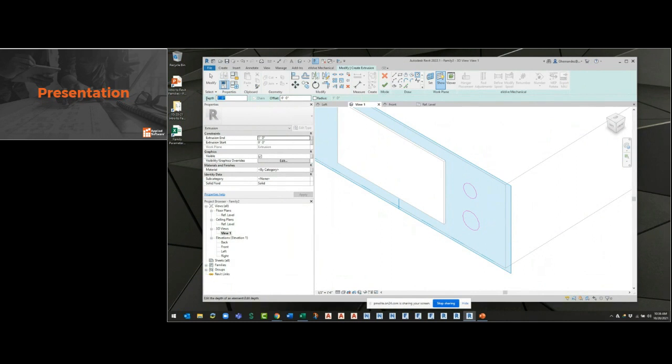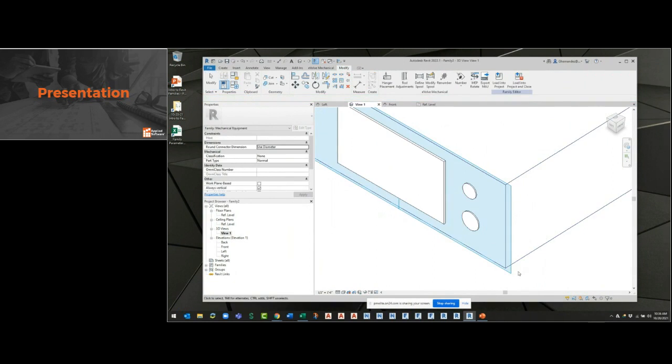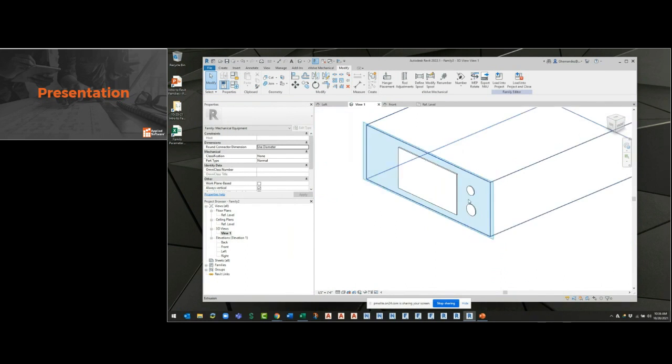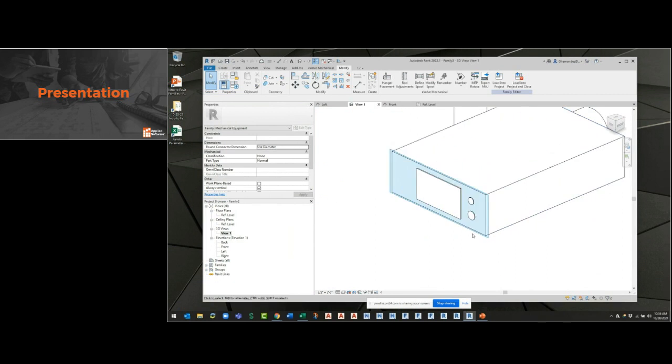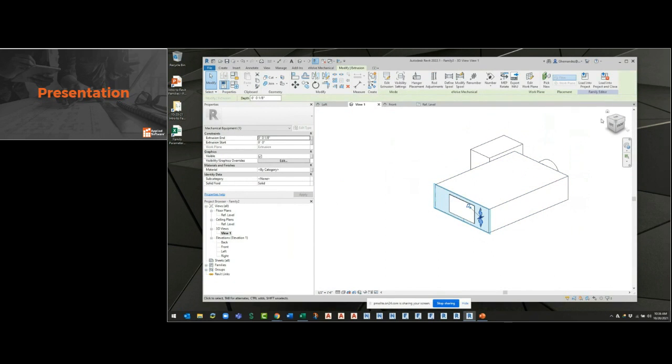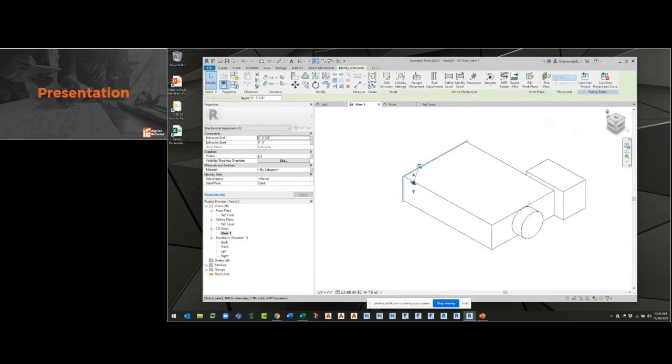And then set the depth of those circles to say like 1/8 of an inch deep. And now I've got some tap outs there that I can put in a pipe or electrical conduit connectors or whatever that I can actually put in a connector. Because you'll see when I place connectors in a bit where these might come into play. Okay, I'm just going to leave those there for now. Those actually should be on the box back there, but I'll remove those in a bit.